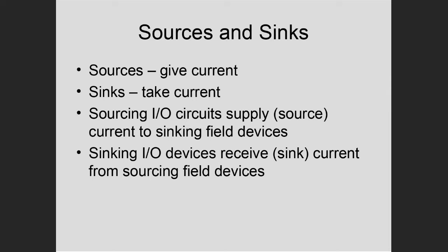That's a normally open relay contact. And that's a normally closed relay contact. So here's what I can do. Instead of wiring up physical switches, I can just drag this literally from my software instruction set. I'm going to drag this symbol onto my screen. I can drag another one onto my screen. And if I want AND logic, I just put the two instructions in series like that.